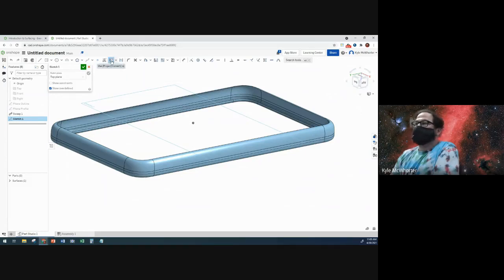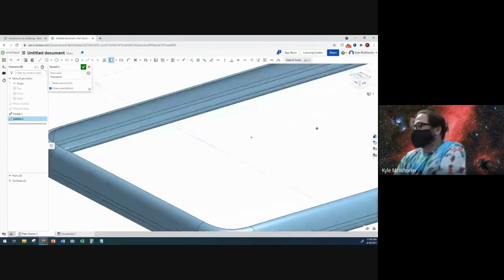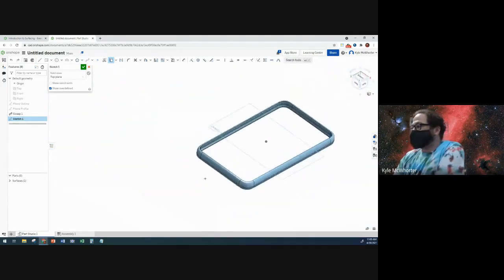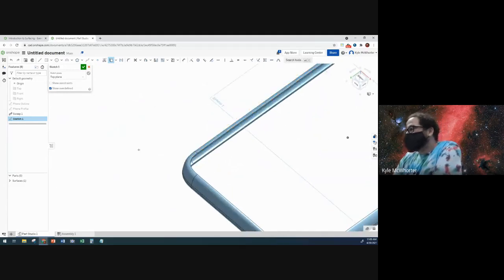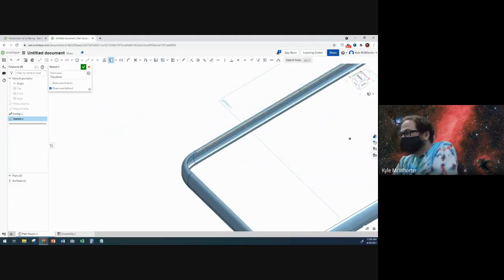which looks like just a box. And we're going to be careful to select the very inside edge of the bottom here. Picking other lines will give you different geometry. Like if you accidentally click a segment over here or down here, it'll give you lines that you don't want.